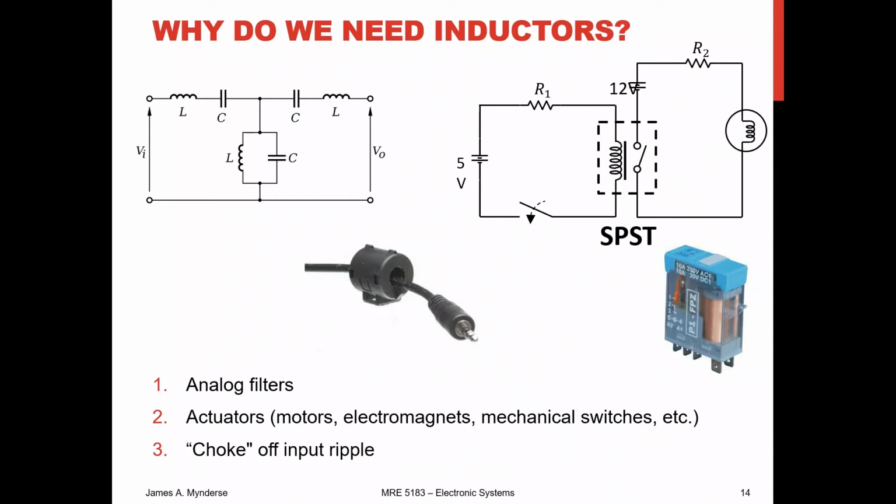You'll also see them in terms of mechanical switches a lot of times. Here's an example right here. We've got a lovely switch that you energize one part of it in order to flip the switch. When you think about relays, there are mechanical relays, and there's also solid state relays that don't have that mechanical element. But the mechanical relays allow you to separate the high power and the low power very nicely. They also do fail mechanically, so they don't last forever, but they're very nice for separating high and low power.